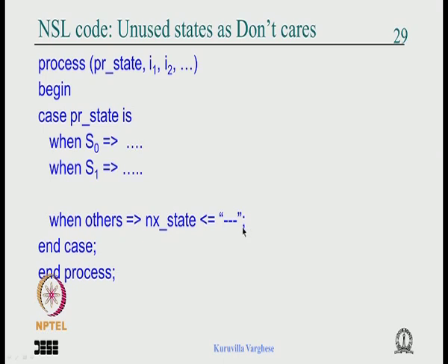We are hoping that if you say don't care, the next state logic area is minimized, because we are not explicitly specifying it. That means for S5, S6, S7 you can treat the next state as 1 or 0, and we are hoping that some minimization happens with the proper assignment and the area gets minimized.